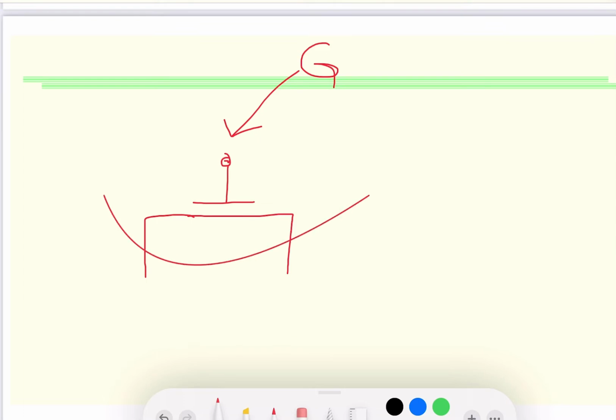The signal will go through and you will get a 1 at the output, a high voltage signal. But if this is turned off, we will not get a signal at the output. So in a way, we can see that high and low levels of voltage can be achieved by turning the switch on and off through the gate voltage. So we are operating this transistor either in the on position, the triode region, or in the cutoff region, which would be the off position.